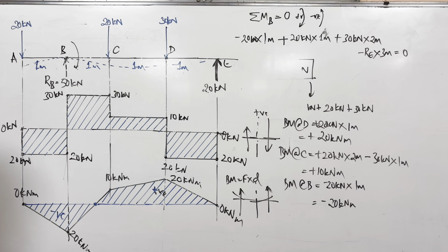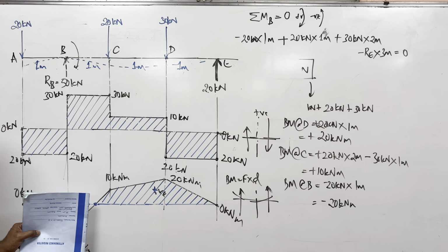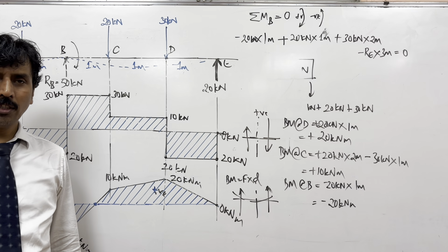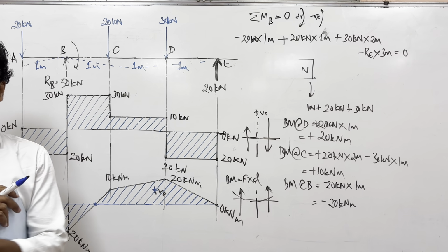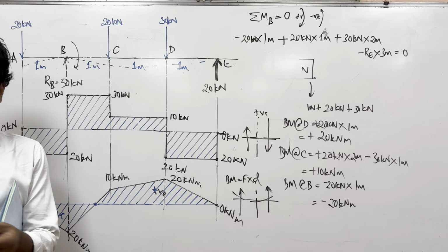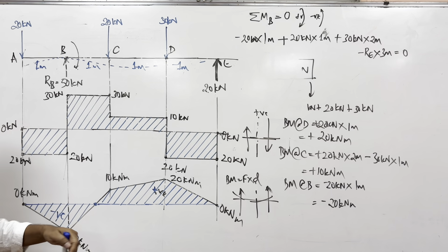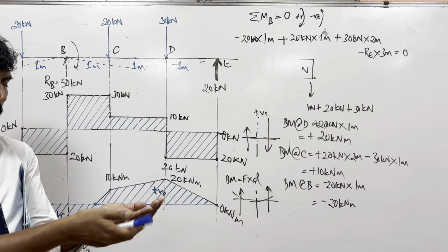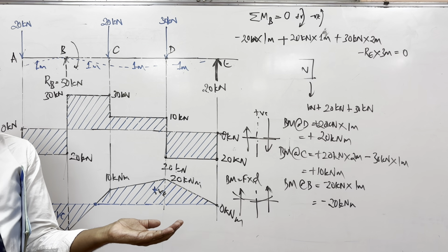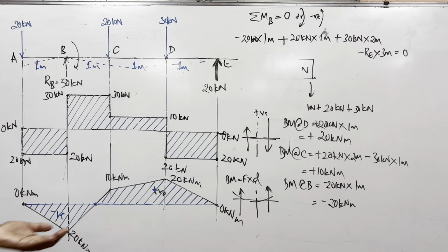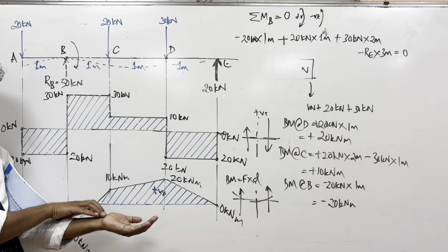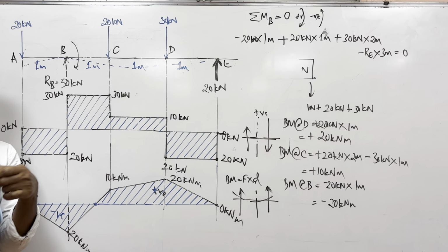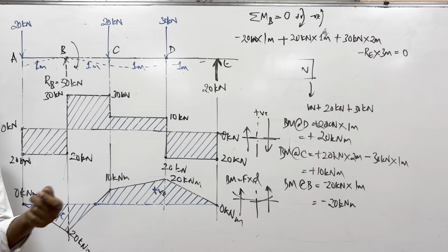It is also important because the engineers need to worry where to strengthen, whether you need to strengthen from the bottom side or the top side. Anything which is bending like this will have compression at the top, then you will have tension at the bottom. And in this part of the beam it goes like this. Again you will see the tension at the top and the compression at the bottom. Wherever there is tension, the material can crack due to tensile failure.